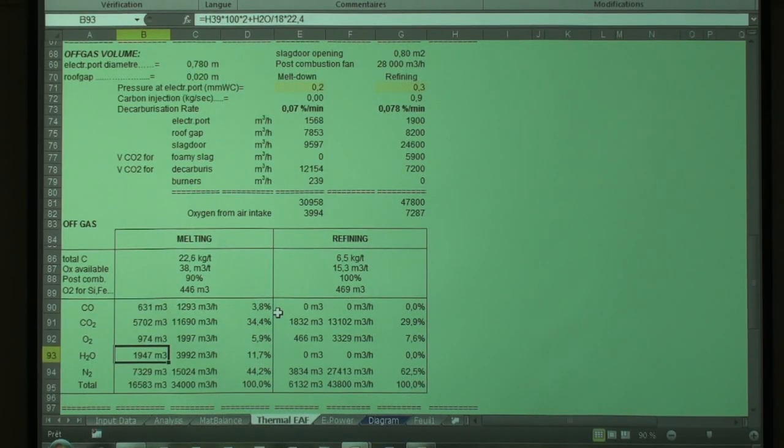When we use the oxygen, the consumption of the electrode increased. People preferred to increase the primary oxygen injection instead of the post-combustion. So they have removed the post-combustion nozzles and installed more supersonic lances. This is more efficient. Yeah, I think so.